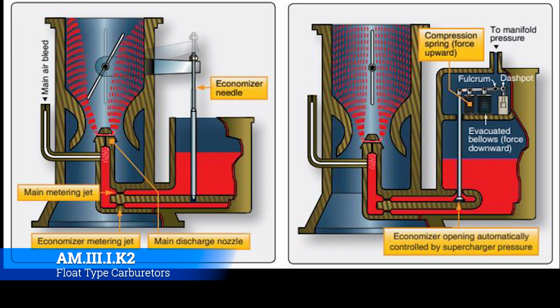Below 60%, it basically shuts that excess fuel off and doesn't let it get into the chamber. But above 60%, it enriches the fuel so that way you can have the max amount of fuel that you need, plus that extra little bit that you need to cool the sidewalls.